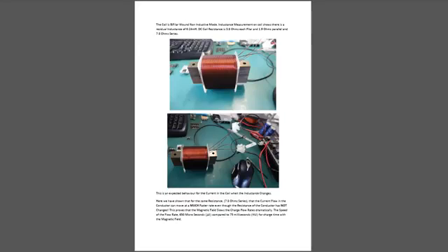DC coil resistance is 3.8 ohms each filar, 1.9 ohms parallel, and 7.8 ohms series. This is an expected behavior for the current in a coil when the inductance changes. Here we have shown that for the same resistance, 7.8 ohms series, the current flow in the conductor can move at a much faster rate even though the resistance of the conductor has not changed. This proves that the magnetic field slows the charge flow rates dramatically.